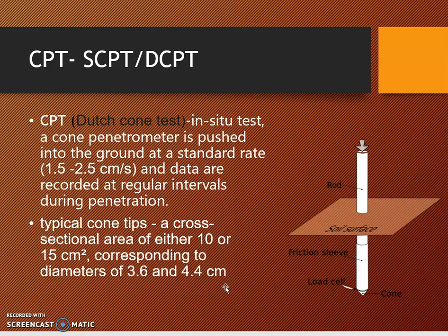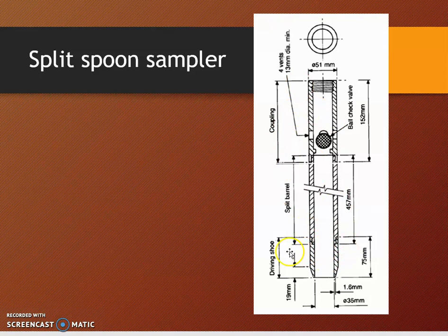Now, soil is not always under dynamic loads. Very seldom is it under dynamic load, right? So these values reflected by N will not be applicable for soils which are under static loading. So there can be a little bit of discrepancy. SPT values, that is N values, represent the penetration resistance of the split spoon sampler. If you remember what a split spoon sampler is, it's that rod. This is a split spoon sampler.